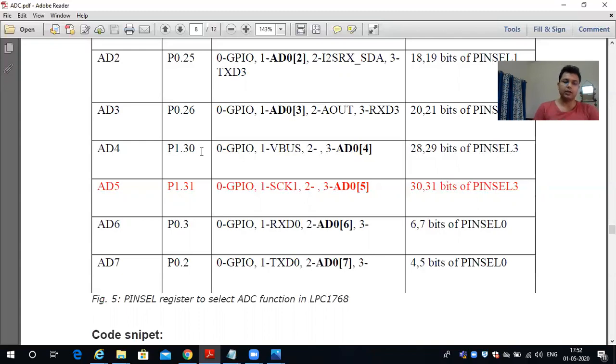One more important thing I want to mention here: ADC always requires voltage as input. As in the example of the temperature sensor, it may be possible that another analog sensor does not produce output in voltage. But if we want to pass it through the ADC, then we first have to convert that analog value, which is not in voltage, into its approximate voltage in some way.